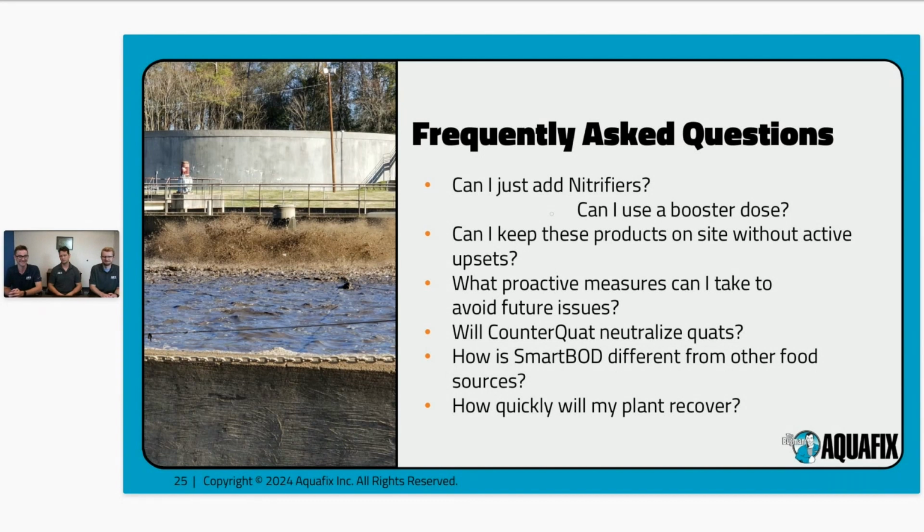Once again, with all the other issues we talked about today, daily microscopy is number one. Yeah. If you can get in front of a microscope, it doesn't even have to be daily, maybe once a week, you can get an update on your plant. We always say, or at least I always say, it's like taking your plant to the doctor's office. It never hurts to get a checkup. You can stay on top of it, and any issue, whether it's toxicity, filaments, midge flies, you're always going to see it in microscopy first.